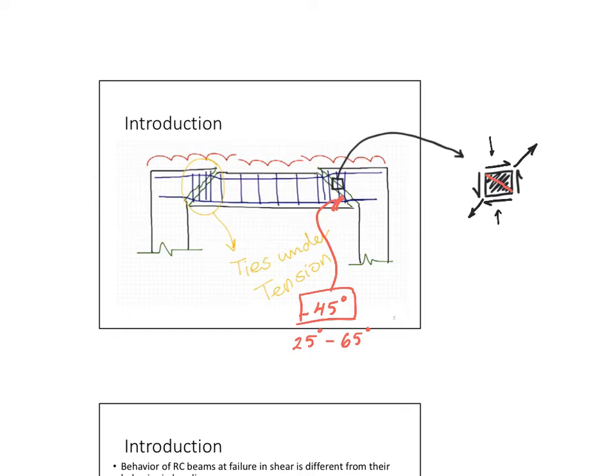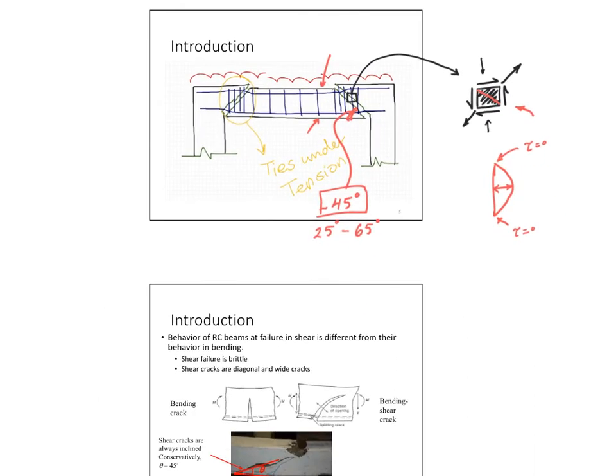Now you will come and say, what if I don't have elements or concrete above or below? For example, like the edge here and the edge there. I would say get back to solid mechanics, and you will remember that the shear stresses looked something like this for such a member, which means the actual stress at the top and the bottom equals 0, right? And the reason for this is that you don't have elements above or below that can resist such rotation. So the stresses end up being 0, and the maximum stress is at the middle because you have the most amount of concrete above and below the middle.